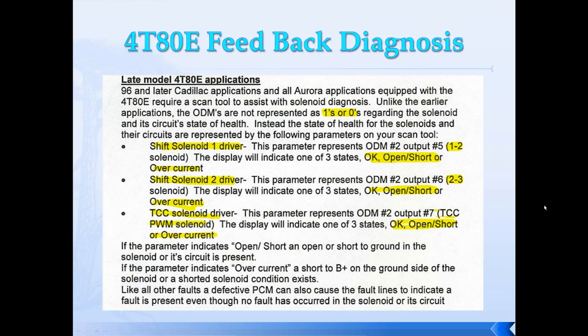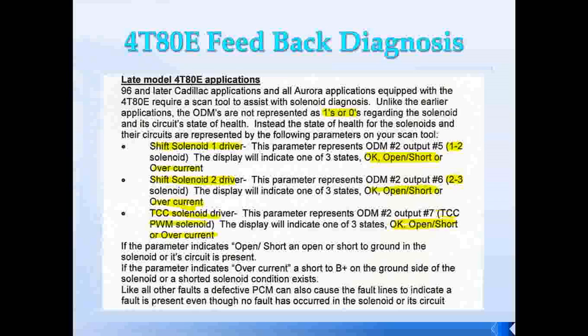We'll allow a few more seconds. Looks like we got everybody that's voted, so I'll close it out, and we'll share the results of this. Looks like everybody pretty well has it right. The correct answer is B. Solenoid command status should say on. So if it says on for command, feedback should also say on. Very good job, guys.